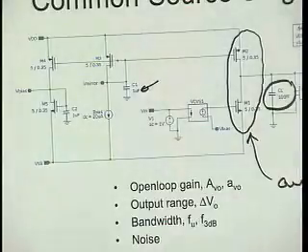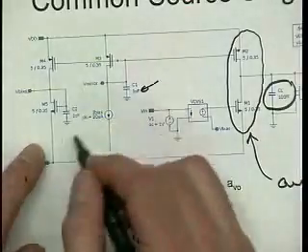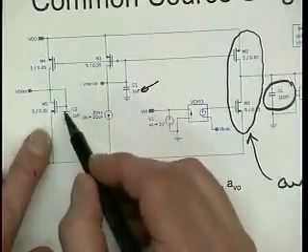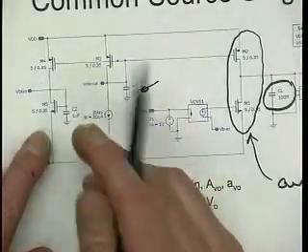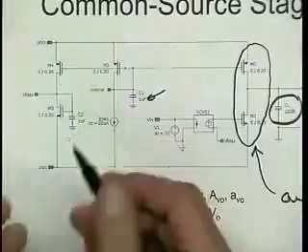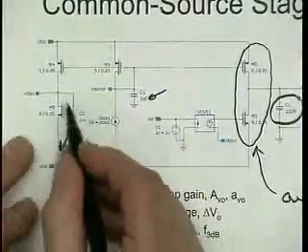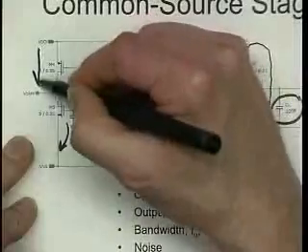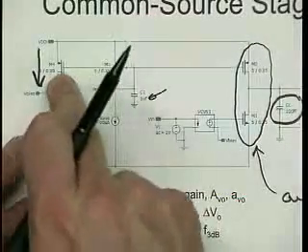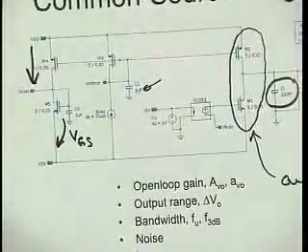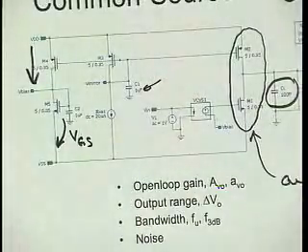Well, I figured that out with a similar amplifier that I just provide feedback between the input and the output. And so it produces the correct VGS here, so that the transistor of this size runs precisely the current that I stick into it, and because the current here and here is the same, the VGS is also ought to be the same. Just yet another way on how to do that. There are 100 ways to do that.